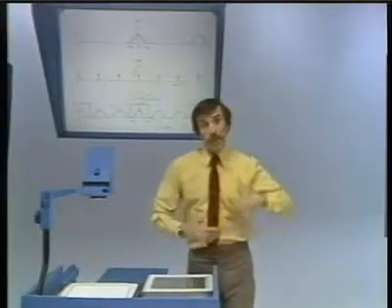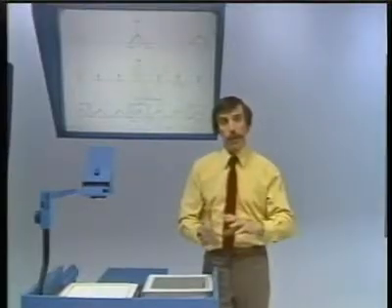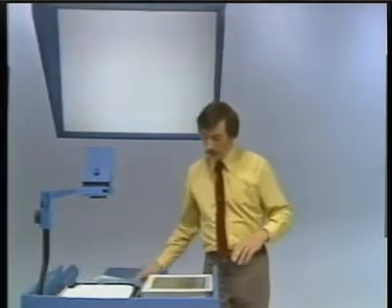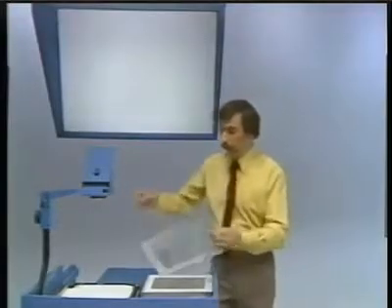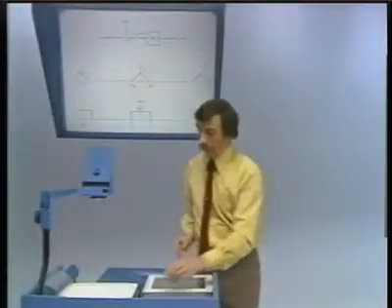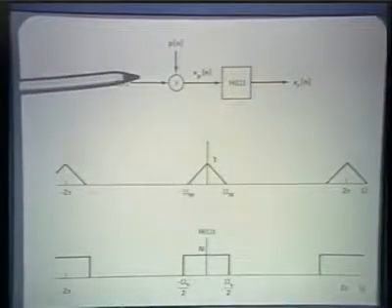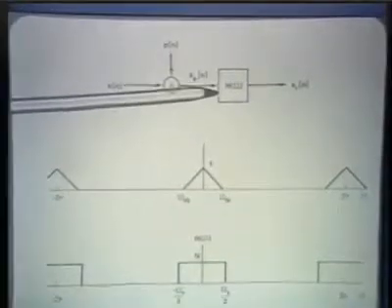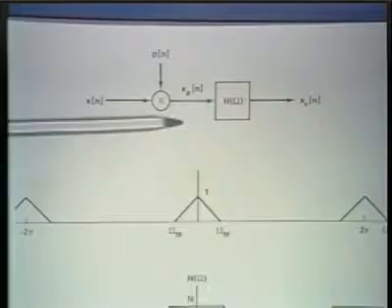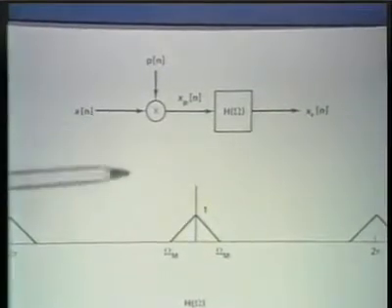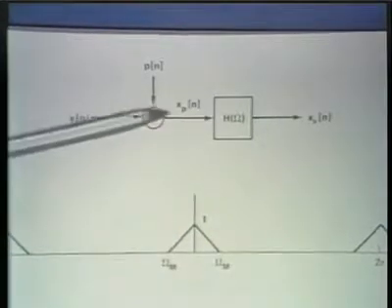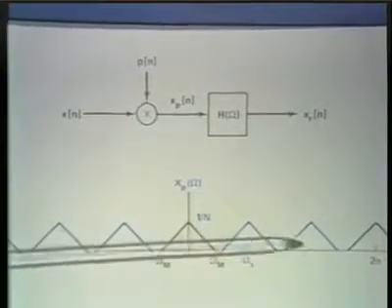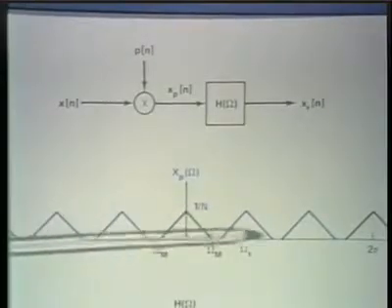So what we see, again, is that the process is very much the same. As long as there's no aliasing, we can recover the original signal by ideal low-pass filtering. So the overall system is, just to reiterate, a system which consists of modulating the original sequence with a pulse train or impulse train, and then that is going to be processed with a low-pass filter. The spectrum of the original signal x of n is what I show here. The spectrum of the sampled signal, where I'm drawing the picture on the assumption that the sampling period is 3, is now what's indicated, where the original spectrum is replicated.